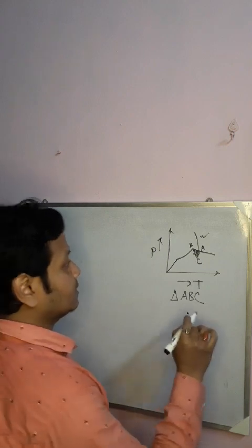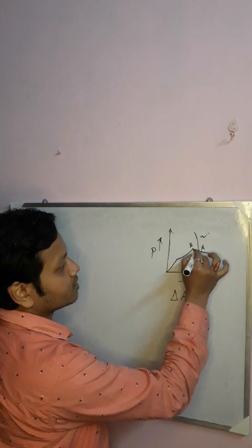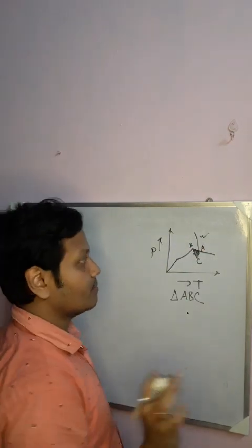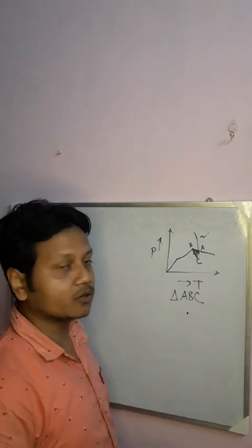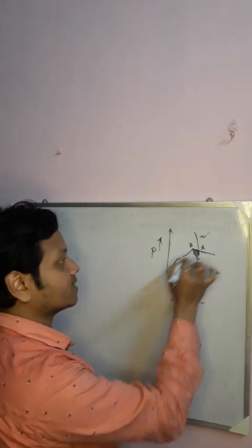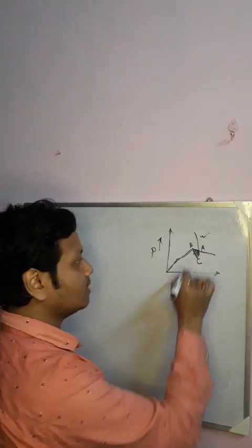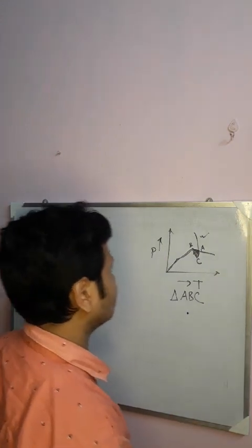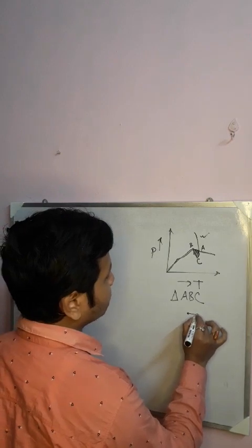If they do not meet at a particular point, but are confined within the shaded region, then according to the ice line the matter must exist in solid state within this entire region, according to the vaporization line in liquid state within the entire shaded region, and according to the sublimation line in vapor state within the entire region. But this is not possible simultaneously.